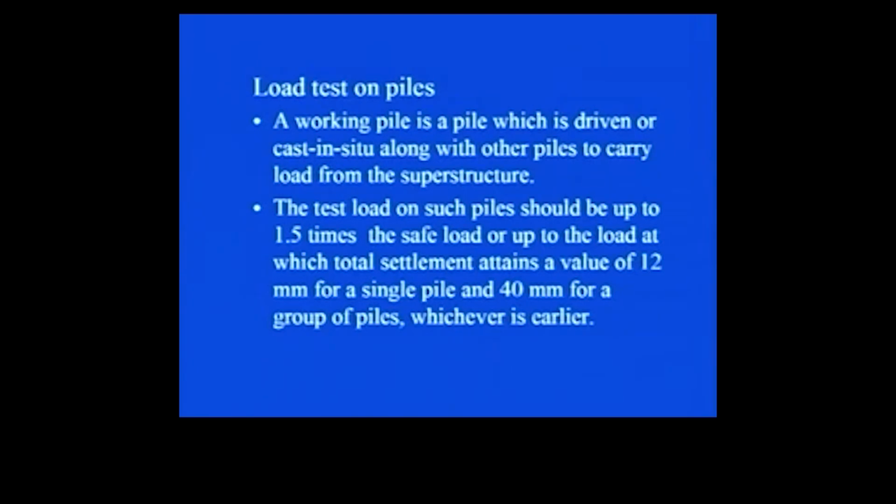Let us say if I talk of a single pile, then there are two criteria: either 1.5 times the safe load which you have found out from the static pile load formula, or the load corresponding to which it has attained 12 mm settlement. Whichever occurs earlier, that much load this working pile should be subjected to. However, in case of a group of piles, the two criteria are either 1.5 times the safe load or 40 mm